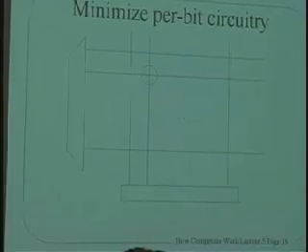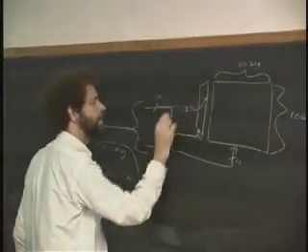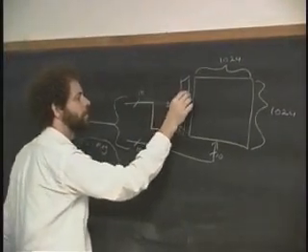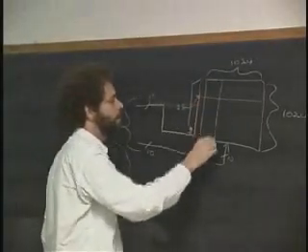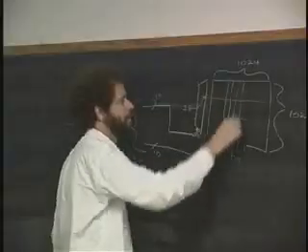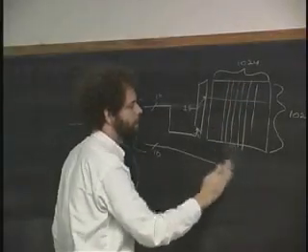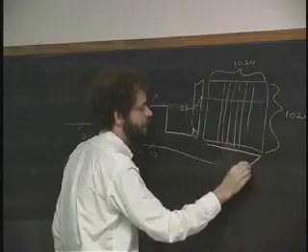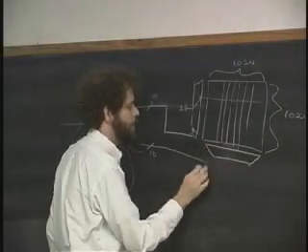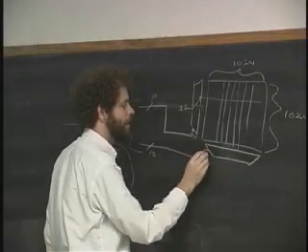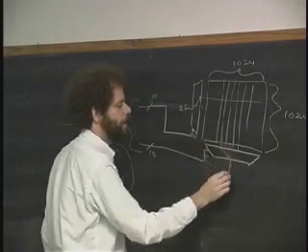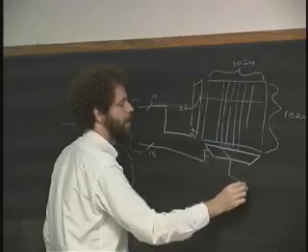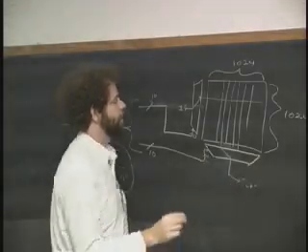10 bits go in here, and I'm going to put a logic 1 in there, and that's going to choose one of the rows. Okay? And then all of the columns are going to come down like this. And what I'll do is I will have a selector down at the bottom. And I'll take my 10 bits and put those into there. And that will choose one of the 1,000 different columns, and out will pop the bit that I want. The bit that I love, okay?